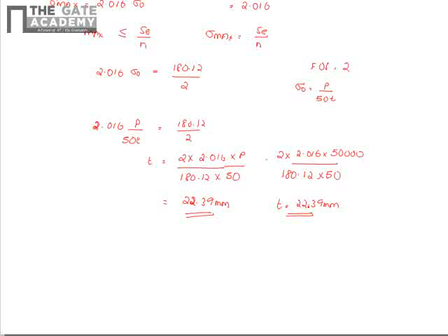Once we know the theoretical stress concentration factor, which depends only on geometry, and the notch sensitivity factor of the material, we can calculate the fatigue stress concentration factor. Once we know the fatigue stress concentration factor, we can design the components to withstand any number of cycles. So with this, we come to the end of this module on fatigue stress concentration factor due to holes and notches.